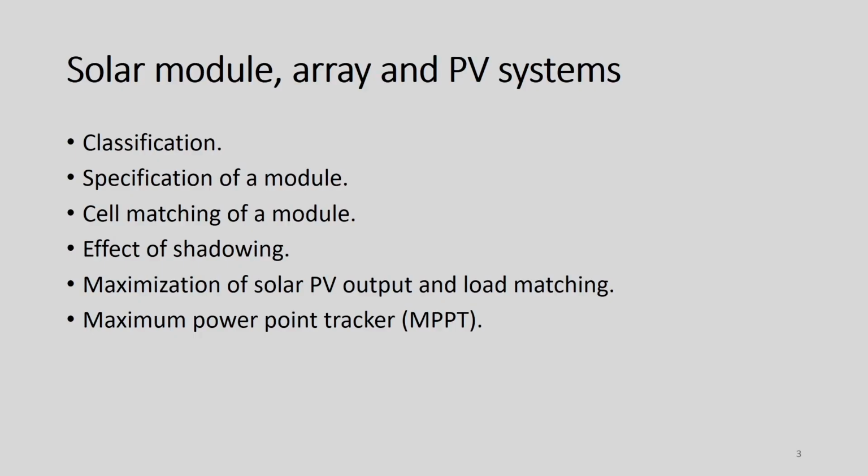Today we will discuss solar module classifications, then specification of a module, then cell matching of a module, then effect of shadowing, maximization of solar PV output and load matching, and finally the maximum power point tracker for the PV system. So what is a PV module?